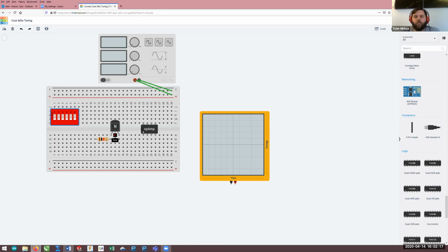We see more use in seeing where something fails versus when something goes right. And I found that in Tinkercad, the more you look at a circuit, the more it's messed up by the multimeters themselves, because there's an internal resistance in those meters already built in. So the more I ask for something to be looked at, the more the measurement's off from the nominal value. And that is greatly appreciated; that was a design feature and not a design flaw.